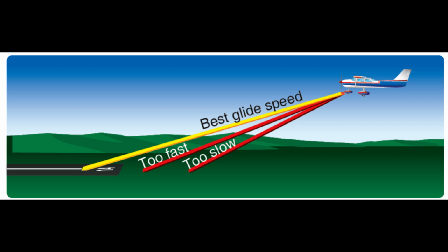Level off from a glide is really two different maneuvers depending on the type of glide. 1. First, in the event of a complete power failure, the best glide speed should be held until necessary to reconfigure for the landing. The pilot should plan for a steeper approach than usual. A 10% lead factor, 100 feet if the descent rate is 1,000 feet per minute, should be sufficient to slow the descent before landing.